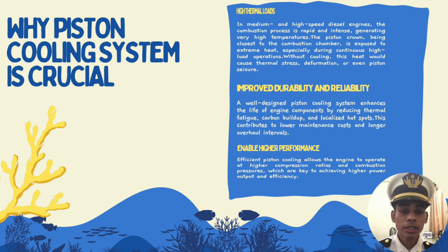Secondly, improved durability and reliability. A well-designed piston cooling system extends the life of the engine components by reducing thermal fatigue, carbon buildup, and localized hot spots. This contributes to lower maintenance costs and longer overhaul intervals. Last but not least, it enables higher performance. Efficient piston cooling allows the engine to operate at higher compression ratios and combustion pressure, which are key to achieving higher power output and efficiency.